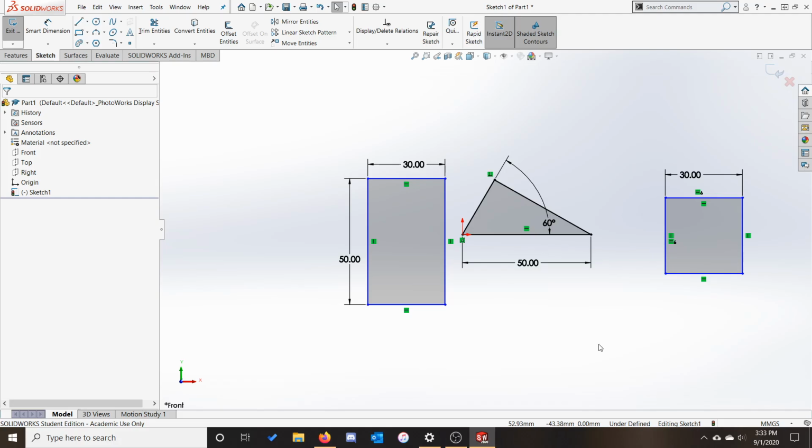Each dimension is an important part of the designer's intent, and acts as a control knob to modify the part. Leaving a dimension out of the model removes that control knob. Repeating dimensions also ignores design intent, as it makes it so that future engineers will have to update multiple dimensions in order to get the intended change, not just one. Calculating dimensions means that any future changes must also be calculated, leading to more work for future users, while also leaving the door open for avoidable mistakes. All of these offenses are considered poor design practice, and a full list of tactics to avoid is available on the website.